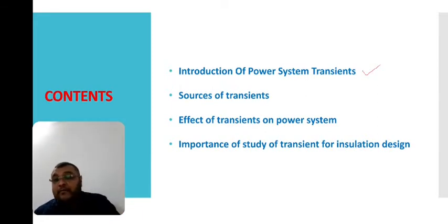When you disconnect a switch or some of the load, when you disconnect the load from that source, or when you open the circuit breakers, that is also one of the reasons for causing the transients. Another cause is if the transformers are forced to operate inefficiently, the windings will become hotter, and that could go into the saturation point.